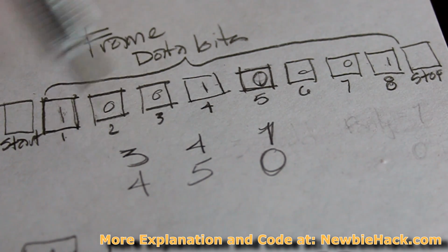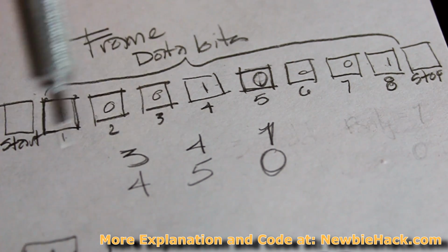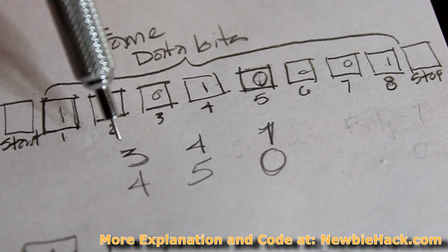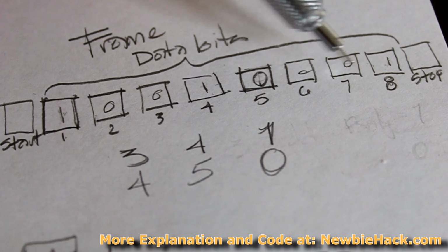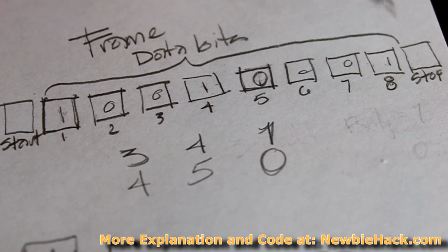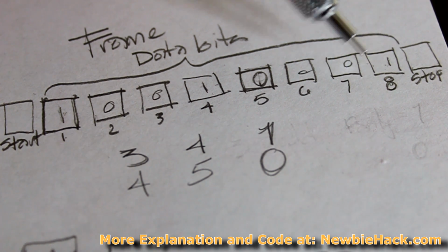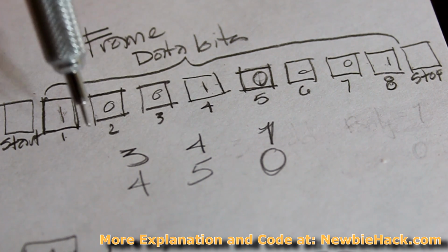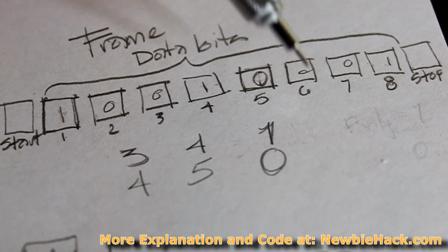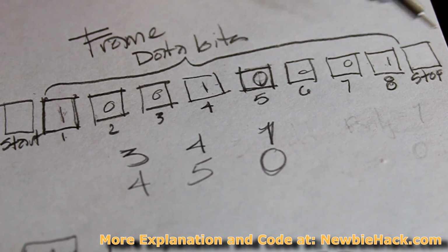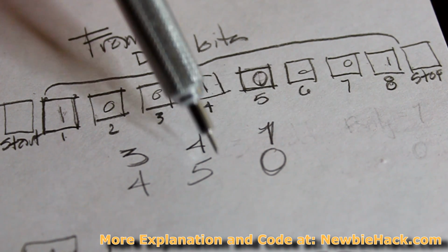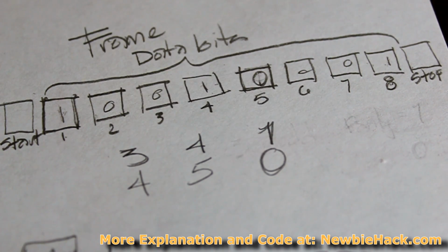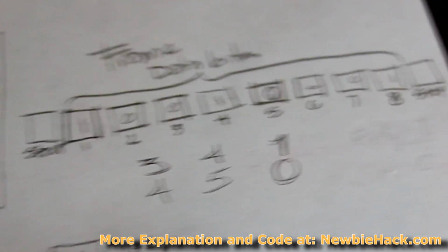And you can have the same thing with odd parity set. So it would be the same thing if the number of ones equal an even number, and then you add the 1 for the parity. Let's say that was 5 with the parity, then that would be a 1 because you set it in the microcontroller as odd parity. And if it came up with an even number including the parity bit, then it would be a 0. So let's look at an example of how parity works.